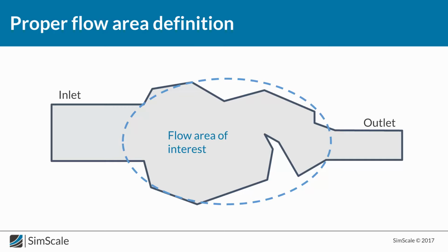The second thing is the proper preparation of the area of interest for the flow. Another thing that we usually do is simply define: this is the open door that we have, and for some reason we want to see what happens. We have an inlet that is a fan. We say this is the face of the fan. There is an outlet. Let's cut it immediately at the level of the floor. This approach is possible and very often will work.